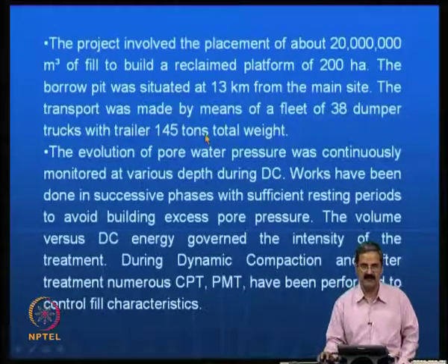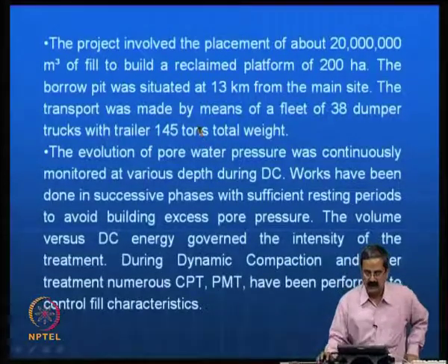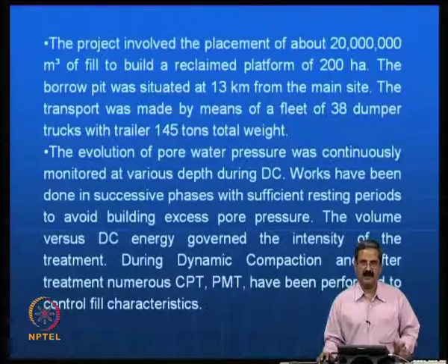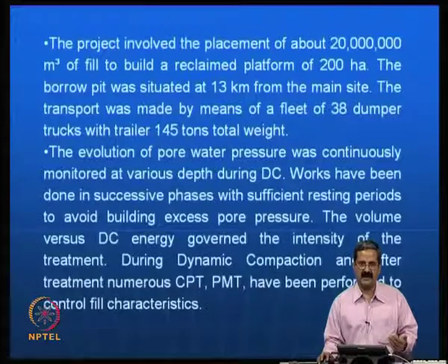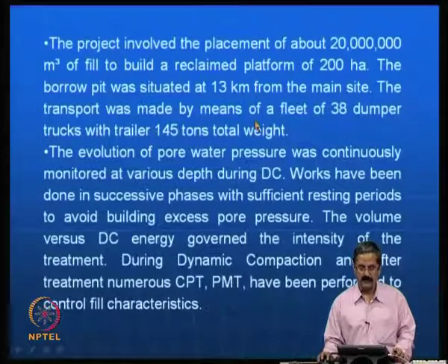You must be able to design even your transportation system very well in a ground improvement project, because you have to get as much material as possible, so that you can start reclaiming and then doing the compaction and then recover the soil faster. So this is a big process involved in the planning of operations for dynamic compaction.